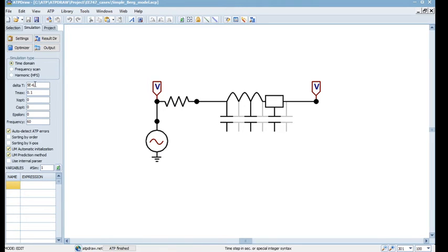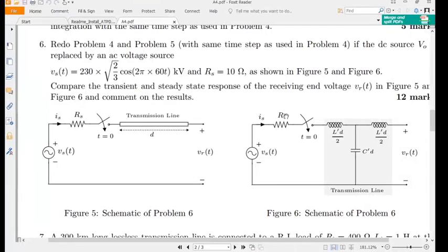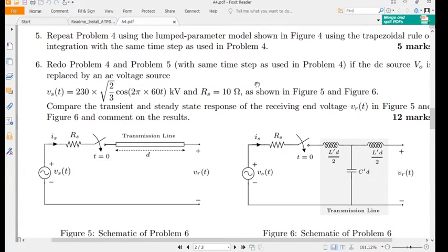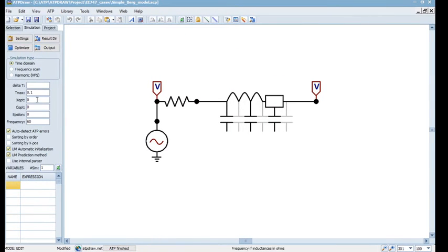Yeah, so how to do that? So first the simulation setting we need to do. So what is the simulation setting? So just to begin with, we'll specify it as 1 micro, but in the simulation you are given some particular value, which is tau times 10%, 10% of the tau value which is available to this transmission line model. Yeah, so instead of that I'll just choose to begin with 1 microsecond. I think it's good enough to begin with, but you should not blindly specify these delta t's. Fine, and the interest will be, let's say, 0.02 seconds, and I'll just save it.